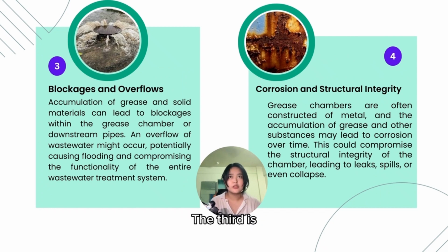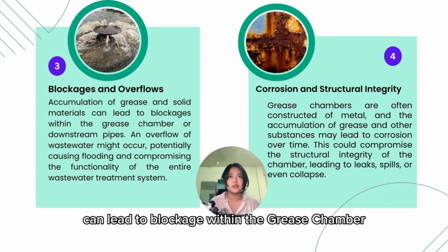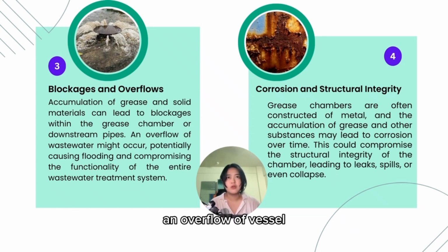The third is blockage or overflow. The accumulation of grease and solid material can lead to blockage within the grease chamber. An overflow of wastewater might occur, potentially causing flooding or compromising the functionality of the entire wastewater treatment system.